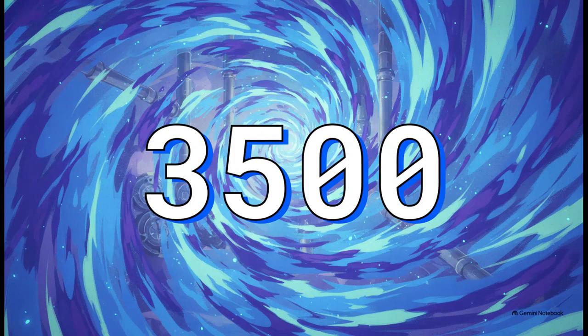Conversely, if the number is greater than 3500, those inertial forces take over. The fluid is just moving too fast for the internal friction to keep it orderly. This results in turbulent flow, which is full of rapid, irregular, swirling patterns. Now, there is a transitional zone between 2000 and 3500, but above 3500 is pure turbulence. And here's a fun fact. Because of the high velocities required, most nuclear facility fluid systems operate entirely with turbulent flow.